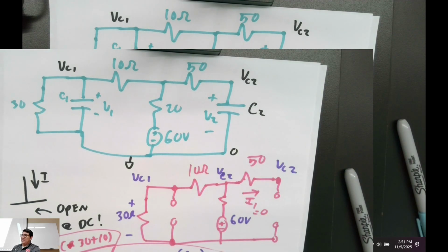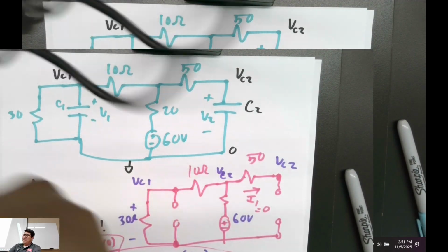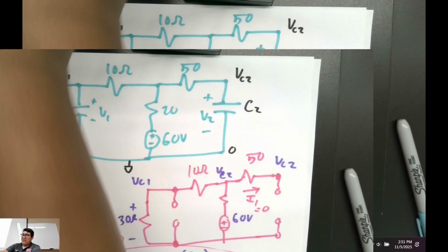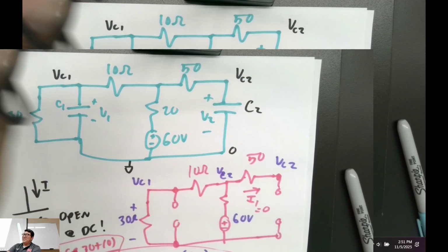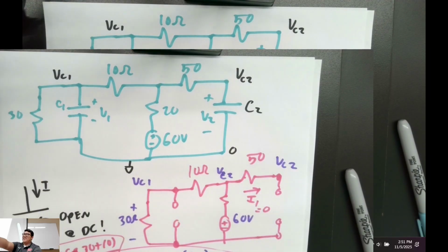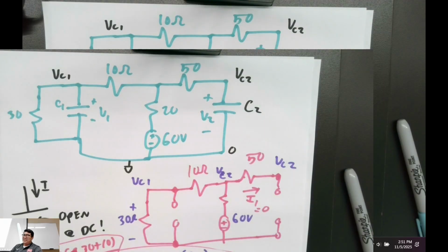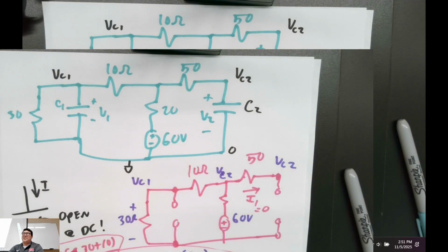So, and then you start realizing, oh, if an inductor is just a coiled wire, right? What does that mean about our grounds in our buildings, or this right here? That means you can start creating some type of impedances, right? When you have these kinds of mishmash, curvy wires. That's why they try to tell you to keep it straight so it doesn't cause noise to go through this, because you'll realize inductors are good at coupling noise.